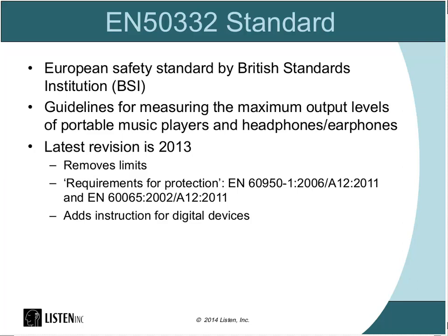In the future, if there's some really good harmonization between these different standards that get widely adopted, maybe then we'll add it into the sequences in a later revision. But for now, we'll just be collecting the data, and then you can decide what you want to measure that data up to. So just as an example, in one of these standards, if your device, the combination of a music player and a headphone, puts out less than 85 dBA, then you're fine.